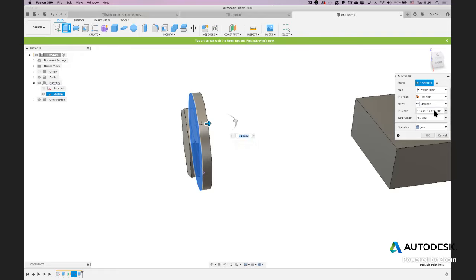It's also been multiplied by 1 just to ensure that all the maths is correct. The other element that's worth highlighting here is that the operation has automatically detected that I'm touching another 3-dimensional surface. So by its default operation it's saying, hey, I see you're touching another surface. Presumably you want to join those 2 pieces together to create one geometry. And that's exactly what that's doing. That's what I want it to do. So I'm going to leave it be and hit OK.